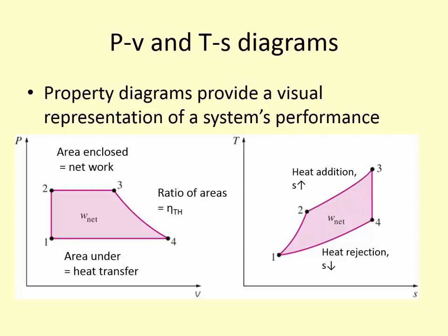And these give us, again, at a glance, a way to compare cycles one to another. We can even overlay them and look at them on top of one another to see how the net power output might increase if we were to change certain components of the system or change the process slightly to a higher temperature, or maybe increase the pressure or decrease the volume.